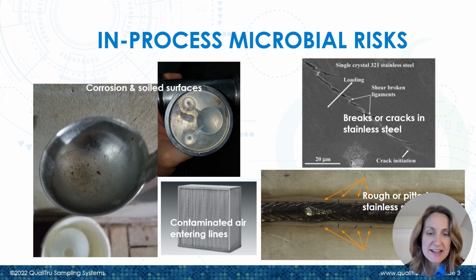This one in the top middle is a valve system that hasn't been properly cleaned. So you see over time, there's a big biofilm building in there. That's then released back into your process. So without good cleaning practices, taking out different clamps or having just good sanitation practices, you can risk contamination.